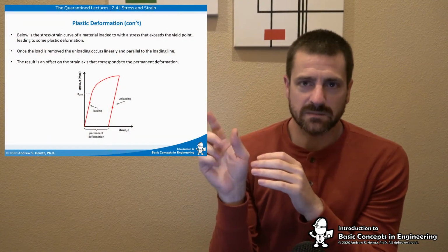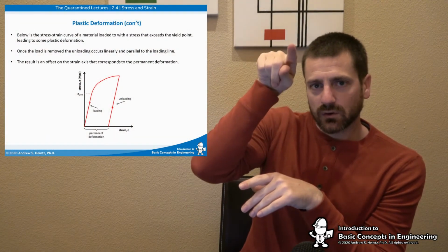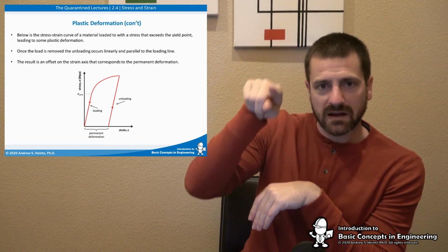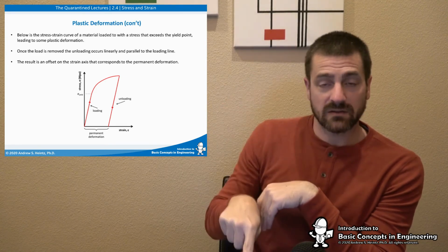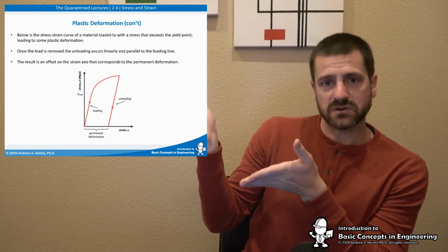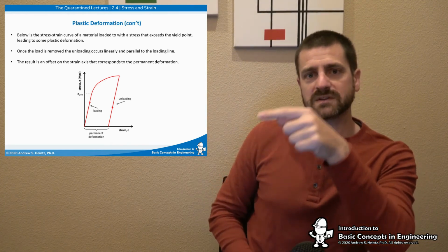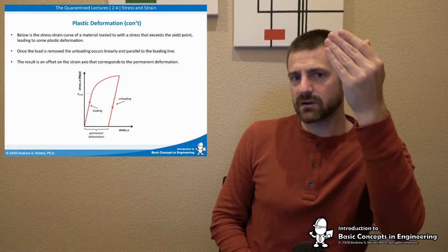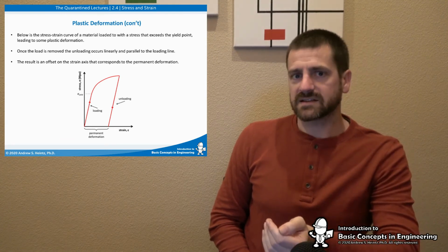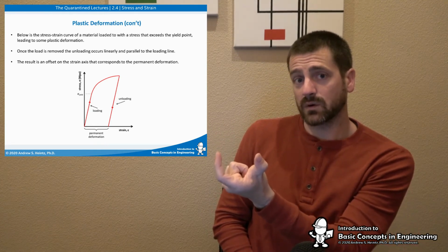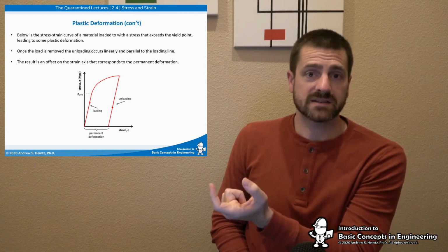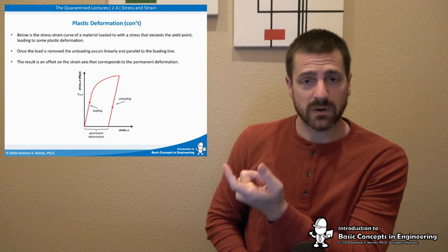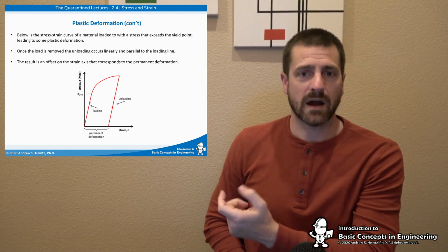Plastic deformation, like we talked about: if you follow this curve and then suddenly stopped putting the load on, you could actually track the permanent deformation by drawing a straight line that follows the elastic unloading, as we show here, right? So what this is showing is, let's say we take it up on a curve to a point where it's still not falling apart, but it's stretched a little. If we draw a line back down with elastic and then look on the x-axis at where that would be, that will correspond to the plastic deformation of the material, how long that material would have stretched and not gone back to its original shape, right? We can actually track that with this plot curve on how much it would deform.